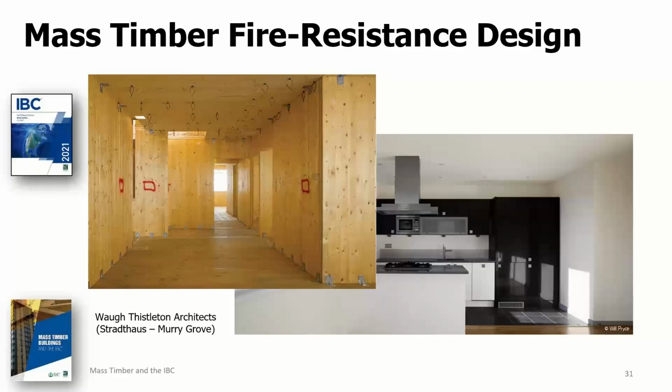In order to achieve a 2-hour fire resistance rating, the designer could simply specify 2 layers of 5/8 inch type X gypsum board on the walls and on the ceiling to provide the additional 80 minutes of fire resistance necessary in order to achieve the full 2-hour rating.